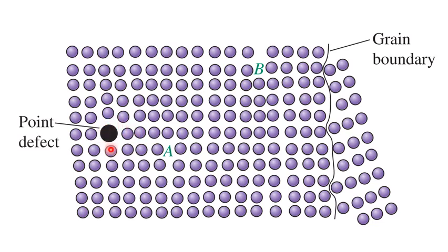Thus we can control the mechanical properties by intentionally introducing point defects, for example, interstitial point defects or substitutional point defects. Both of them introduce imperfection in the crystal structure, and cause an increase in the stress needed for the dislocation to move, or to slip through the structure. This is called solid solution strengthening.